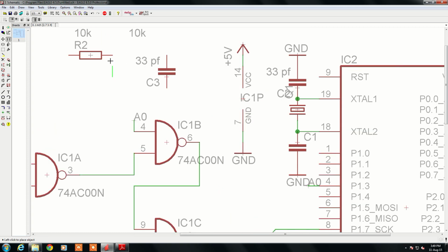and if I place it at this point, now you think that a new line is drawn here, but actually if I use the show command and click this, even this is highlighted, and this is highlighted. That means this and this and this are shorted. So that is why never copy the lines. You always draw new lines.